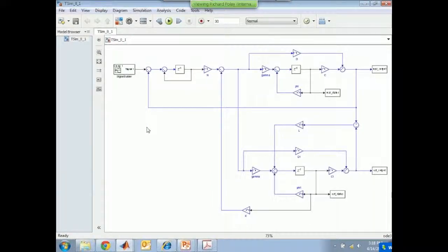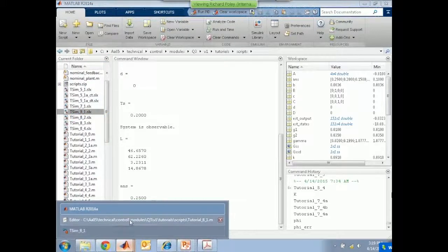So here it is. It's the integrating controller, discrete time, and I'm collecting the real outputs and the real states into the workspace, and we're going to use those a little bit later. And down here, we're using the estimator algorithm, where I am bizarrely using the state from this point, not this point. But anyway, I've got a one sample delay going on that I hadn't realized until just now. But it produces the state vector for us through K, and then we're applying feedback control just as we did before. So let's produce that. There it goes. And then back into the workspace here.